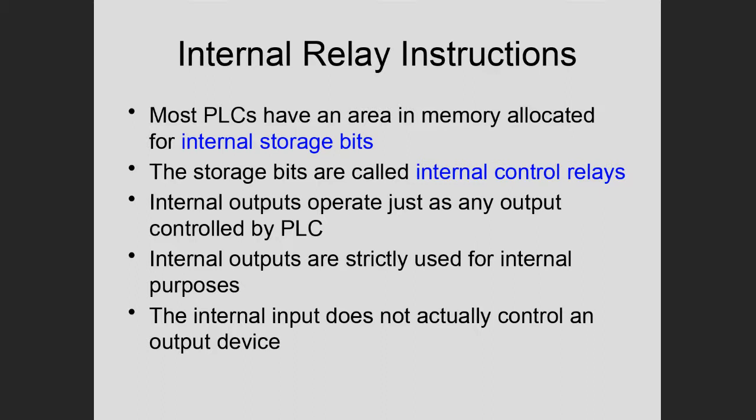Now, most PLCs have a memory for internal storage bits. So these are called internal bits, or if you have an internal relay contact. So an internal contact is a contact that does not access anything outside the PLC. It's not connected to any button or switch. It's all internal. So it's just a 1 or 0 that can act like an internal switch. And so they call that an internal control relay or internal contact. Now there's a lot of things you can do with that, but let me just show you one right here.